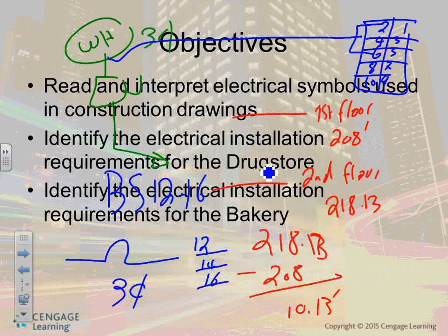Look at circuit number 1. What is circuit number 1 feeding? Let's go to circuits 27, 29, and 31. Is this 3-phase or single phase? 3. How do you know? 3 circuit breakers, or 3 slots. How about circuit 41? What is circuit 41 feeding? Spare, open. The reason I would like you to look at these is that you're going to be generating this in Revit. All this is going to be generated in Revit.